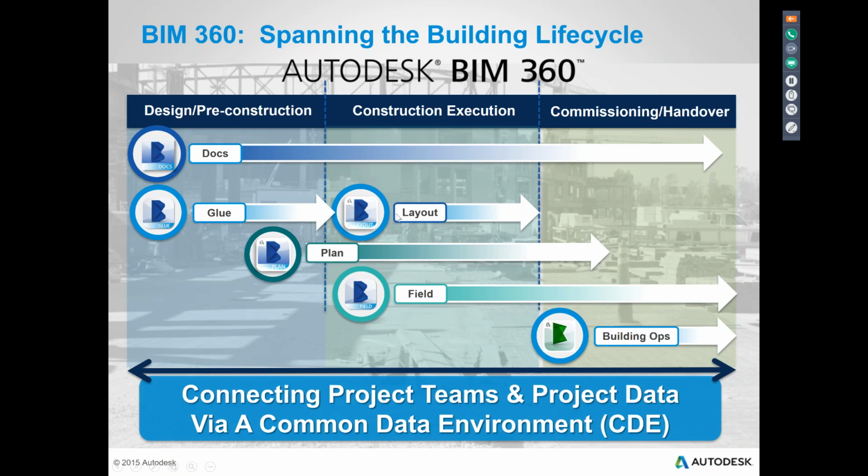And then there's BIM 360 Layout, which is really kind of a two-application tool. The first part of that application is a plugin that runs on top of your desktop operating software. So Revit, Navisworks, AutoCAD, this Autodesk Point Layout, APL tool we call it, runs on top of those applications and automates the placement of points in your models. So 3D points, XYZ points in space on things that are important to lay out during construction. Slab edge conditions, corner conditions, hanger wire locations, embed locations before you pour concrete, lighting locations in the ceiling, really anything that needs to be located that you would typically string out a tape measure on the site.